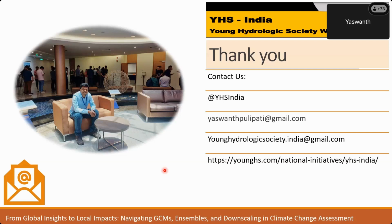And when it comes to dynamical downscaling, it is a continuous run with the physical model, so there is no separation between the extremes and normal runs. We run the models continuously. But when it comes to statistical downscaling, you have different procedures like this. You can separate the rainfall days into less than extreme and more than extreme, and you can use your own distributions or statistical models to fit.